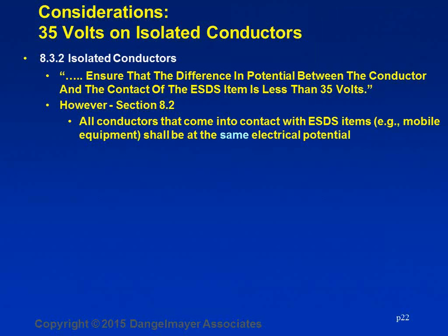So basically, they're saying you've got to ground the conductors, but we all know that in a real-world situation, there may be some conductive items, i.e., circuitry on a board, a ground plane on a board, that you can't ground. And that's the intent of this statement, to make sure that you are looking at those kinds of conductive items and making sure they're grounded. Rotating end effectors on robots is another possible situation where you just can't ground it. And again, we advocate grounding everything you can.